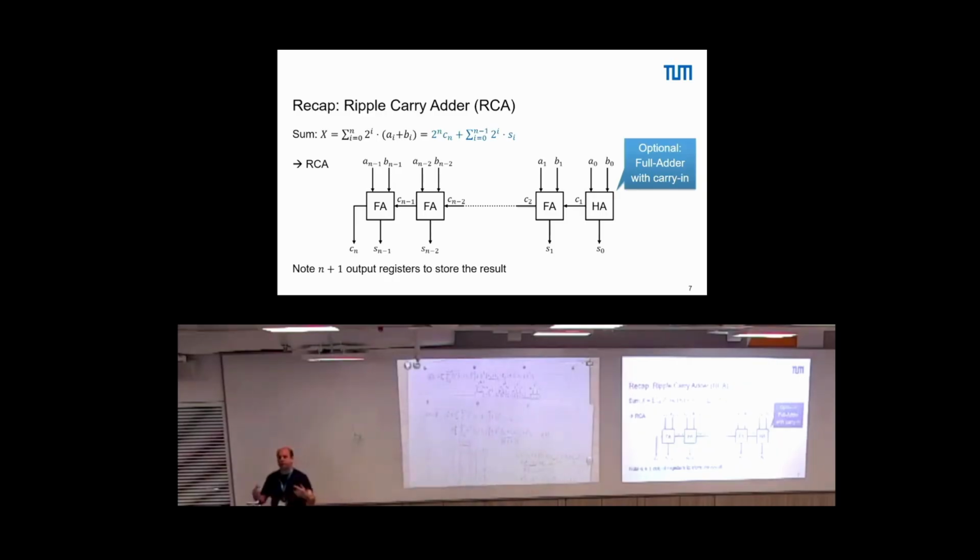So we have this invert and add 1 directly on the fly, just by adding a few gates in between. And the outputs are, of course, the sum or difference bits. That's why 2's complement is so nice, because you can do such tricks with it.